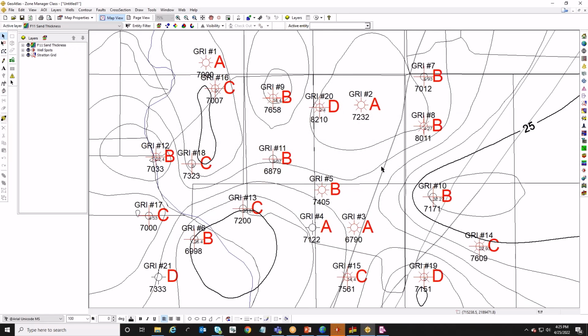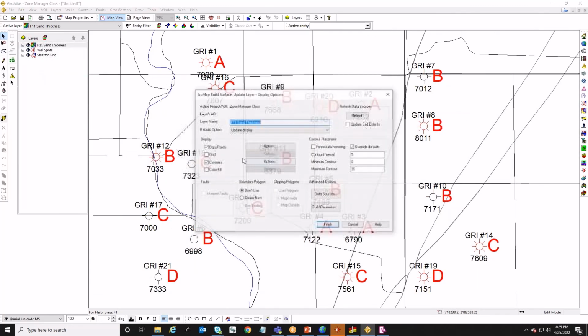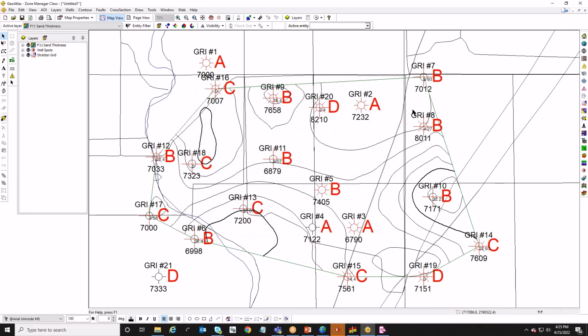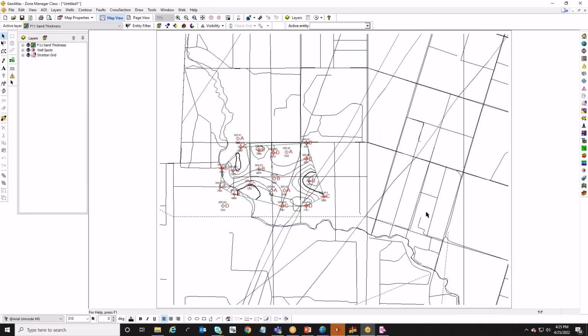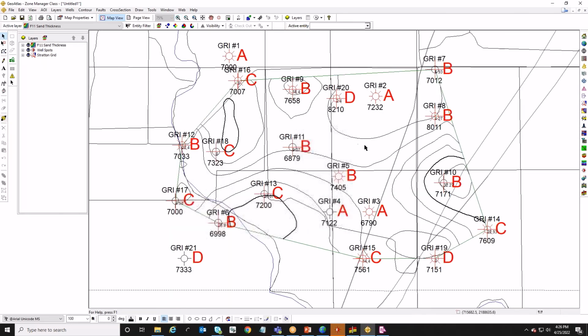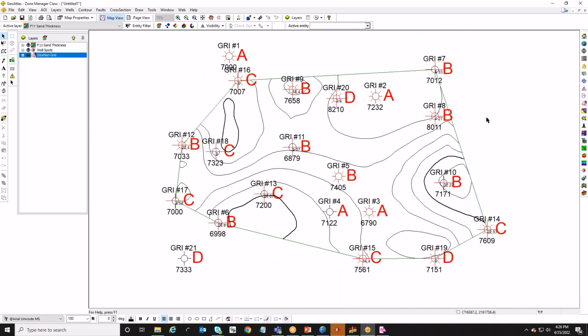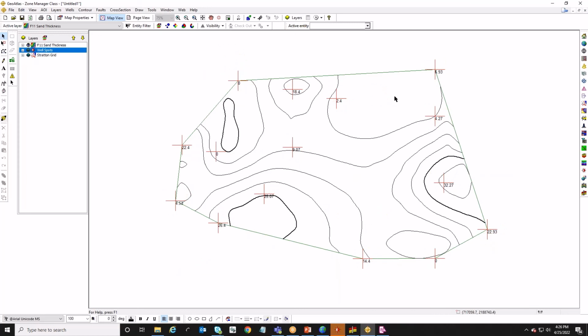Yep, I forgot to put a boundary polygon around it. Two seconds. I'll add that boundary polygon in there just so I can clip all my data to where I actually have my data points, as outside of this there's a bunch of blank space that doesn't have any data points that I kind of ignore. So we'll keep everything in here where the data points actually exist, so that I can get that contour map to indicate behind that grid what that's going to look like. And then I have all the various values associated with each of those data points that I can post.